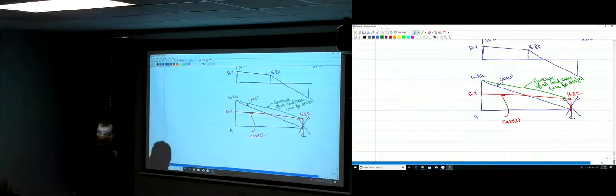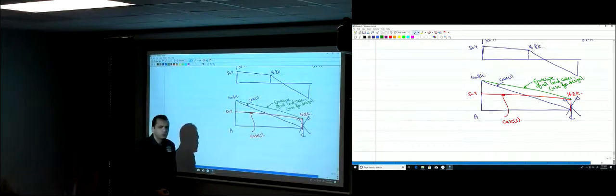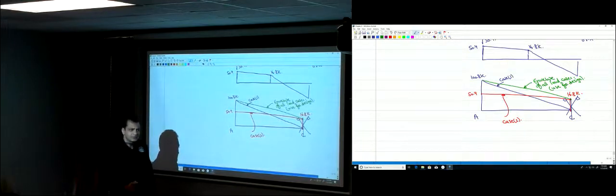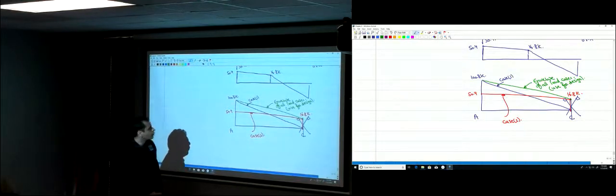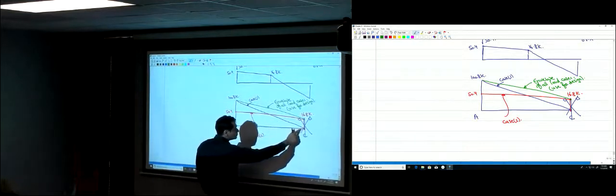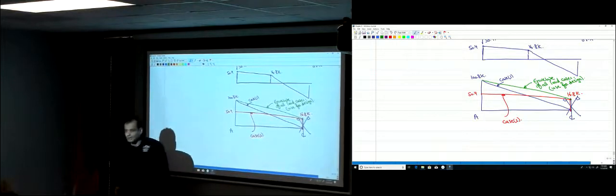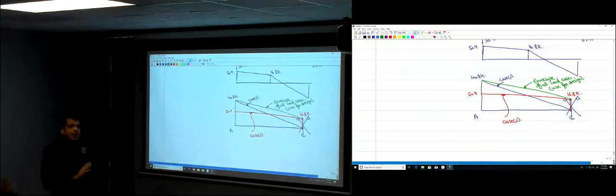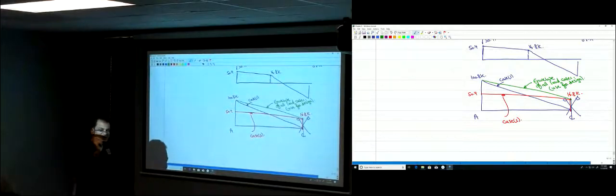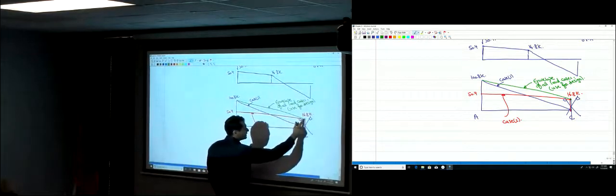So in example 8.3, we solved the same example. But we didn't make use of the load cases for the live load. So the shear force diagram that we got is this blue one. This is what we got. Now, applying the live load so that we maximize the shear force at the midpoint, this is what we get, the red curve.